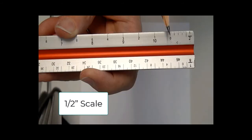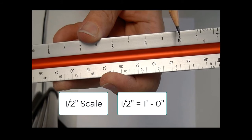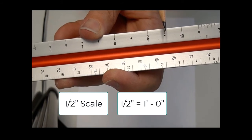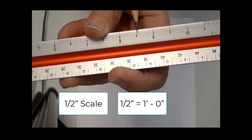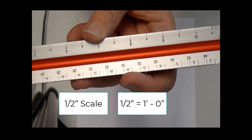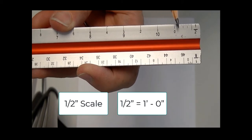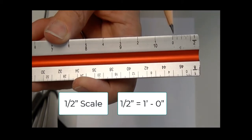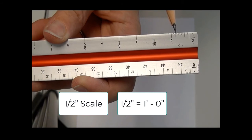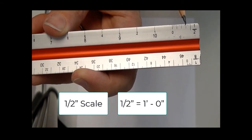The other scale we're going to talk about today is 1/2 inch equals 1 foot. So as I look at the scale, I go 1 foot, 2 feet, 3 feet, 4 feet, 5 feet, 6 feet, and so on. And then when you turn around, we're going to do the inches. So that's 1, 2, 3, 4, 5, 6, 7, 8, 9.